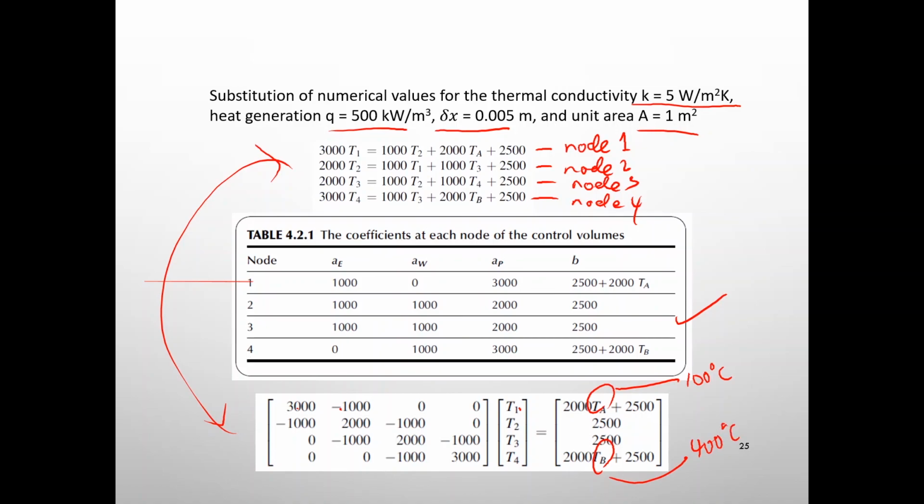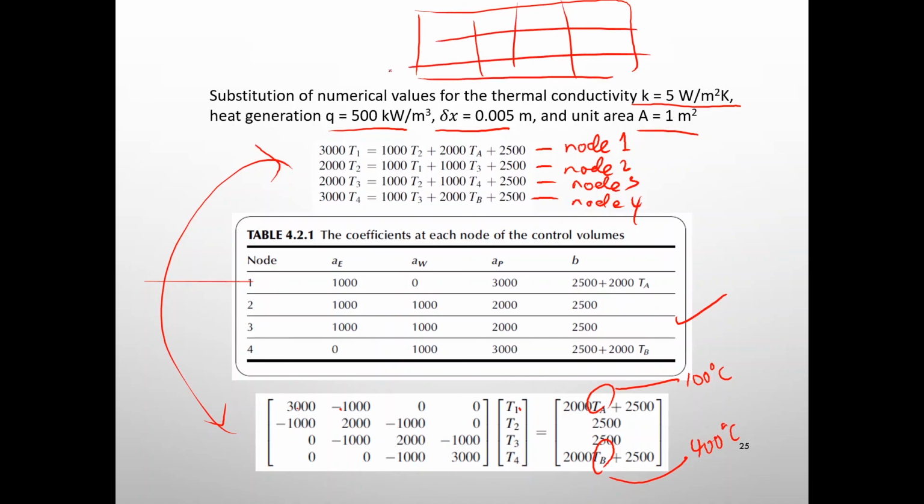So basically this is what all your simulations actually do in the mesh. For example, in the mesh we have a lot of nodes, and we have boundary conditions. For example, temperature equals 100 here, and temperature equals 400 here. Then what the simulation does is calculate the value at each of these nodes using this. And this is only for temperature. If you have momentum equations or advection, it will do the same thing for all your U, V, and W. That's why boundary conditions are very important.